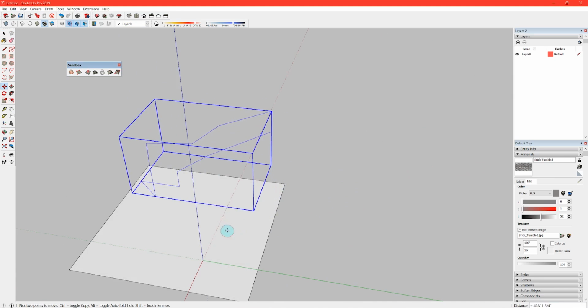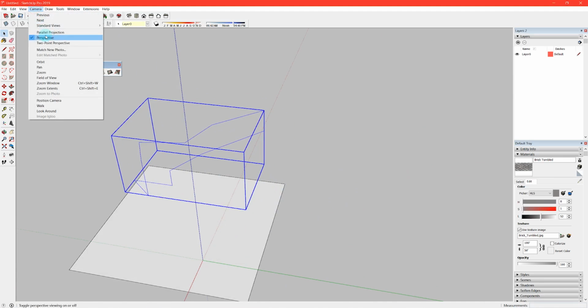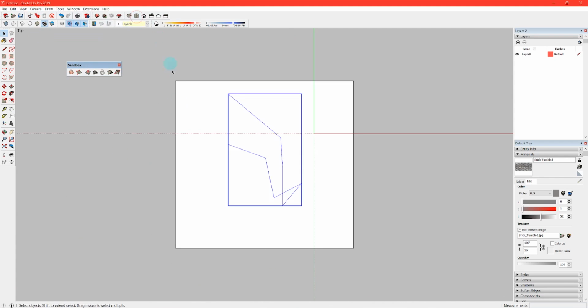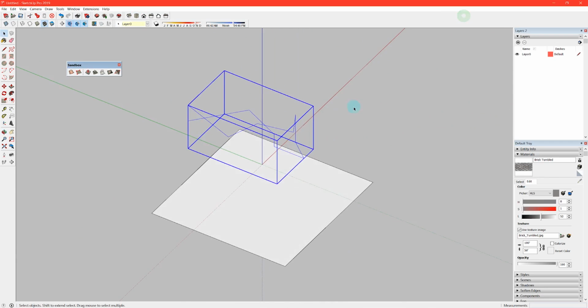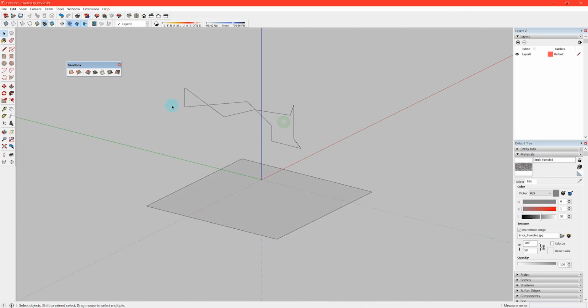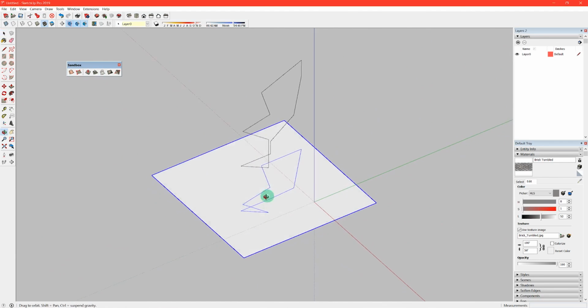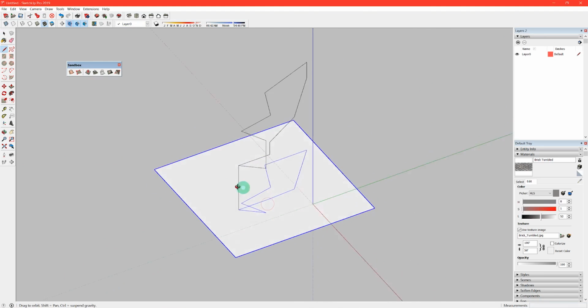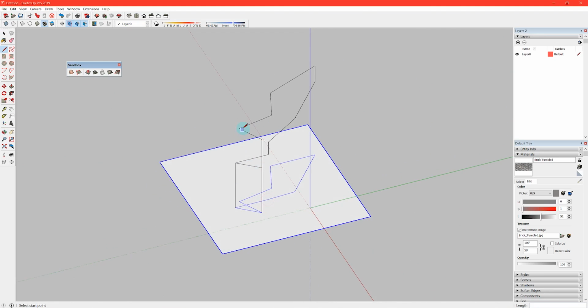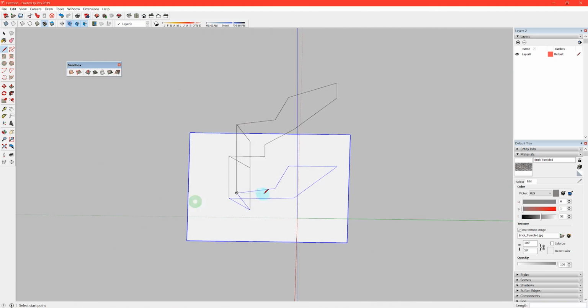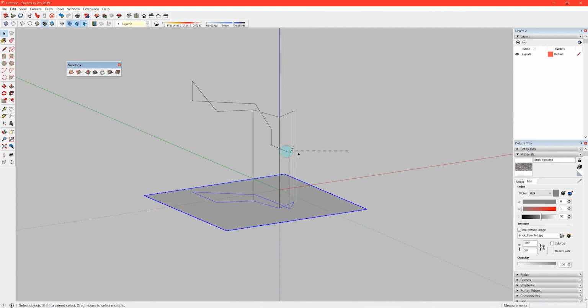But if you position this above a plane and then select that curve and then choose the Drape tool and then click on the face below, it's going to project that curve directly onto that face. And you'll see that for this example, I have some overlap, but essentially it'll take all those points straight down onto that face.